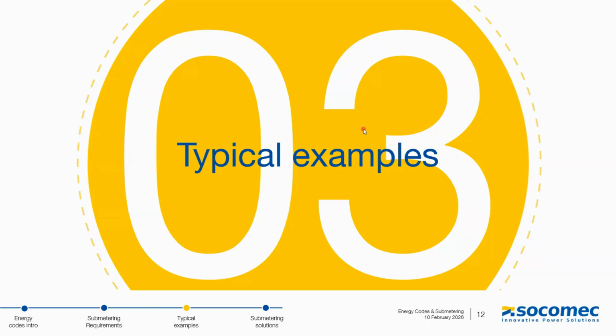You can take a look at the sheet notes specifically in the electrical section to locate any submetering requirement, which is usually where the IECC or the ASHRAE will be mentioned. And something that's a little bit easier is to check on the one line if there's a circled M or a CT symbol. Sometimes it's just going to be a little note that refers to the sheet note. But those are just examples of how to know if that project is asking for submetering. So yeah, all of the answers were correct.